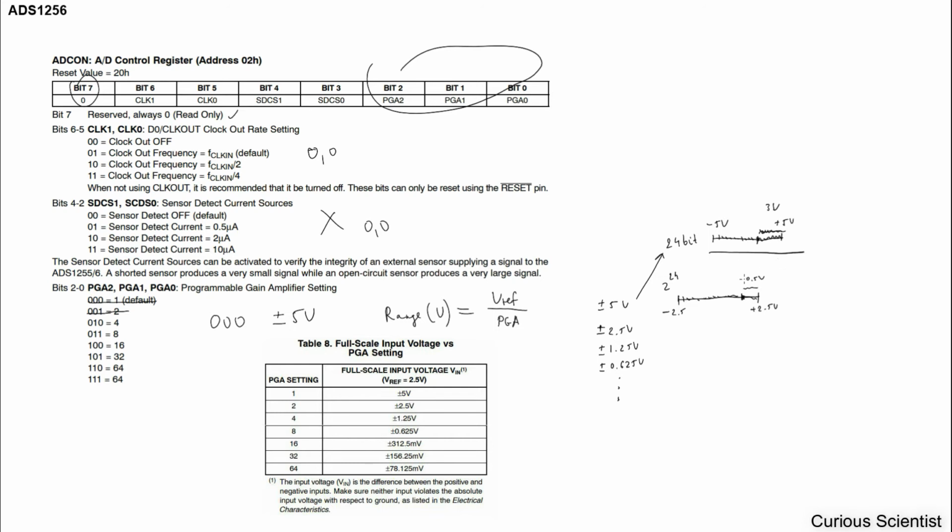It's like when you are using a multimeter and you try to measure the resistance of something precisely. Let's say you have a very low value resistor, let's say 1 ohm. You are not trying to measure it in the 1 megaohm range, because you won't get the value precisely. And here the principle is something like that.